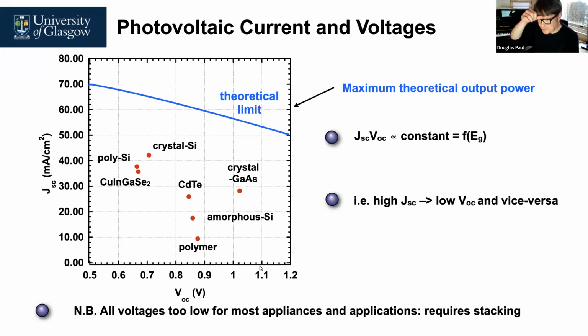Now, in fact, one of the things to note here is the voltages are typically all less than 1 volt. Now, there's also going to be some series resistance in any photovoltaic cell. They can be made low, but there will always be some. Now, in fact, modern electronics means you can power directly with the voltages that are available. But for many of the systems, and particularly for batteries, you're going to need voltages that are substantially larger than 1 volt. So you have to stack the photovoltaic cells to increase the voltage. You also have to look at modules with stacking either parallel or in series to get the appropriate current and voltage that you want as output. And you're also going to need power conditioning to be able to power circuits with the right current and voltage.